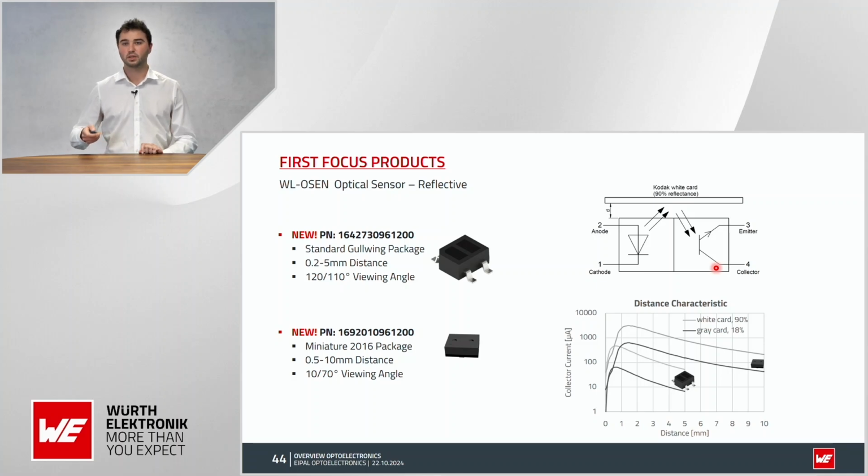Because of this, of course, you can have much more space efficient usage, and it works also really nice. So you don't need to take care of any crosstalk between the LED and the phototransistor, because we have a barrier already built inside of the package. So the first products that I have here for the optical sensors, they are really useful only for small distances, like a few millimeters range.